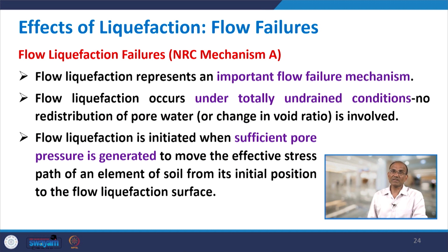Flow liquefaction failures, NRC, there are different steps for this. So, NRC mechanism A is listed here, what the National Research Council's mechanism says. Flow liquefaction represents an important flow failure mechanism. So, if liquefaction is occurring, that itself is an important indicator. Flow liquefaction occurs under totally undrained conditions, no redistribution of pore water pressure or change in void ratio is involved.